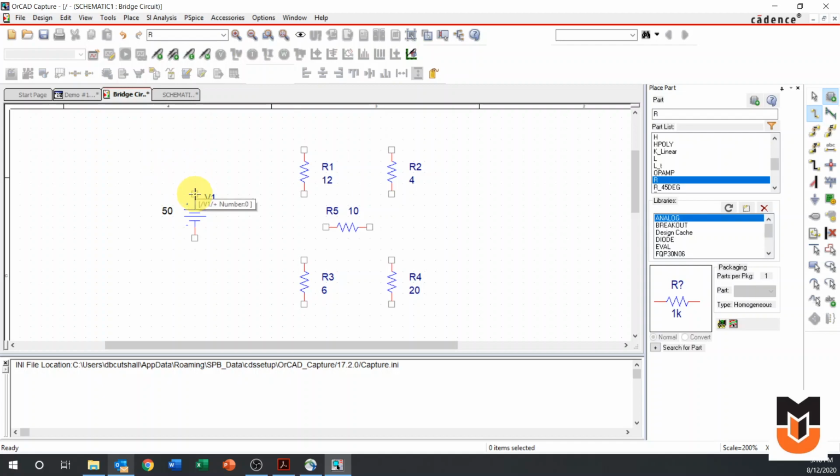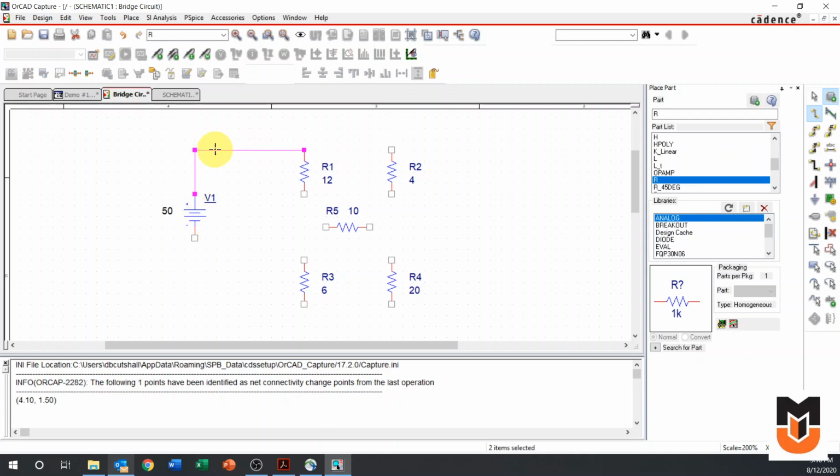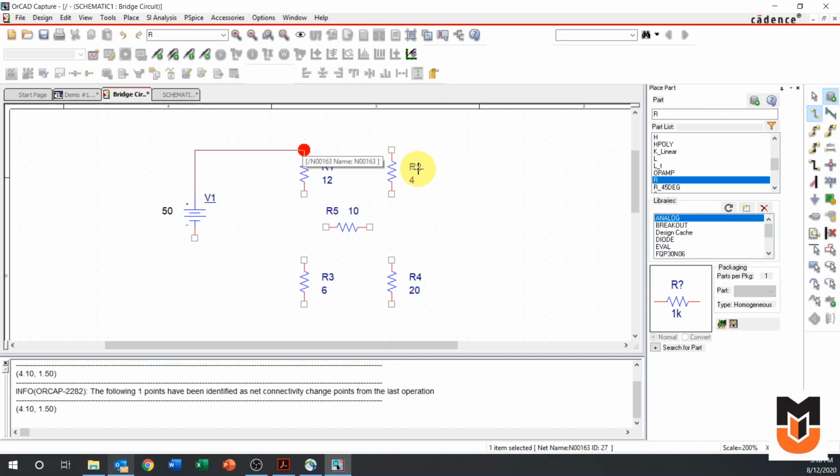So I'm going to come over to one side of the component and left click. That's going to start my wire. I'm just dragging, not clicking, and I can connect it here by left clicking once more. So once I do that, it connects the wire, and notice I no longer have a wire following my cursor, but I still do have this crosshair indicating I'm still wiring. So I can left click and left click to connect these, and let's left click, connect there, and again I'm just left clicking each time to connect these, and so it'll just auto bend for me there, and I can just connect this right here, and that's going to connect.